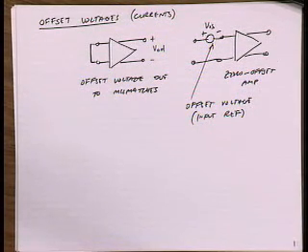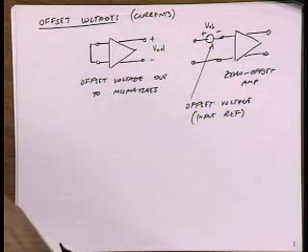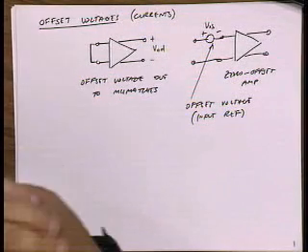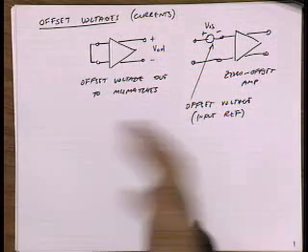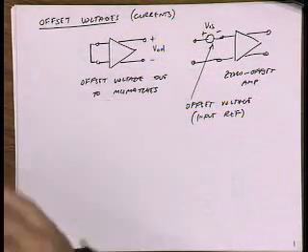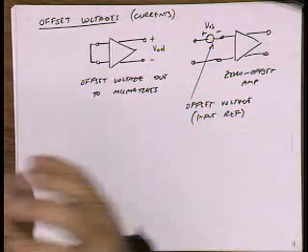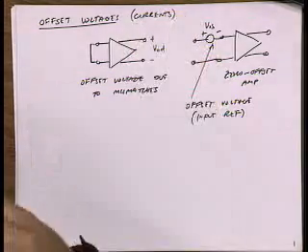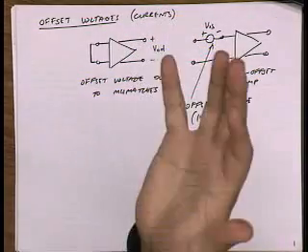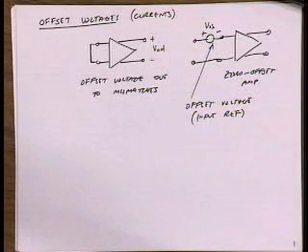Is it because the gain is big enough that you can have enough gain? Yeah, it's very good. If this amplifier has a lot of gain, let's say a gain of 1,000,000, what happens when I put a microvolt on the input? The output swings 1 volt differentially. If my supply voltage is 1 volt, then a tiny 1 microvolt input can actually rail the amplifier. What's wrong with railing the amplifier? Well, the gain goes to 0. You go outside the range where you actually have gain for your amplifier.